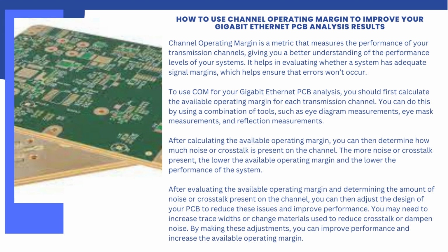You may need to increase trace widths or change materials used to reduce crosstalk or dampen noise. By making these adjustments, you can improve performance and increase the available operating margin.